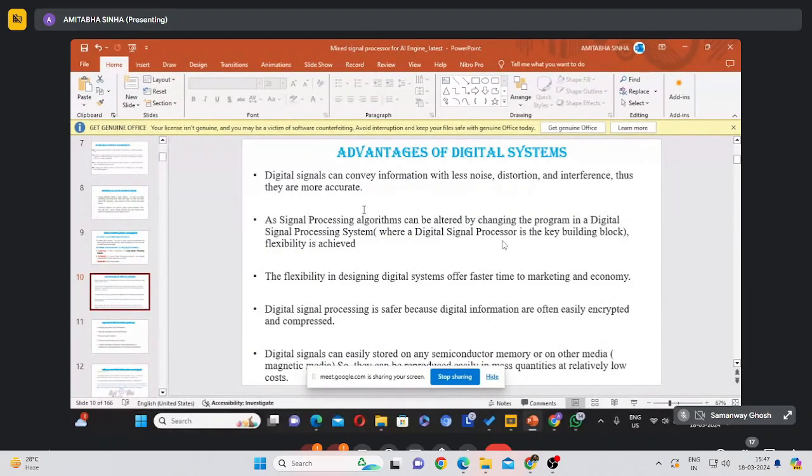Say you have an LCR circuit. All of you have studied the LCR circuit. Let's say the input is a voltage signal and the output you want to take across the resistor or capacitor, anything. There is a relation, and that relation can be described by Kirchhoff's voltage and current equations, given by differential equations. If v(t) is the input voltage, it equals i into R for the voltage across the resistor, plus L di/dt, the voltage across the inductor, plus 1 by C integration of i dt. So it is nothing but a differential equation.